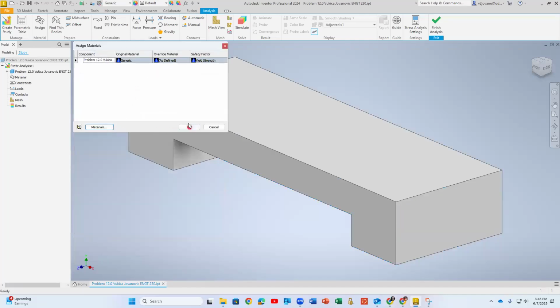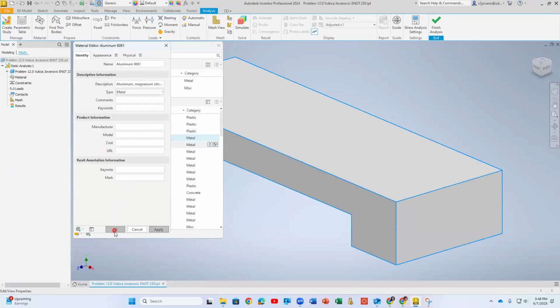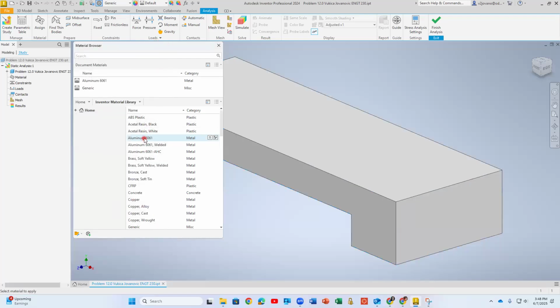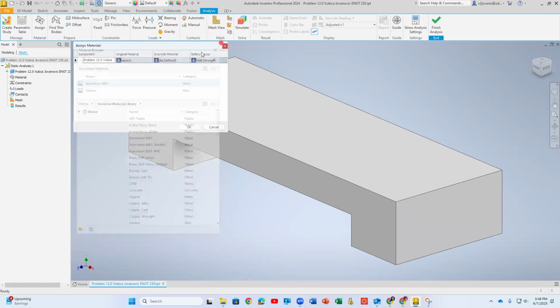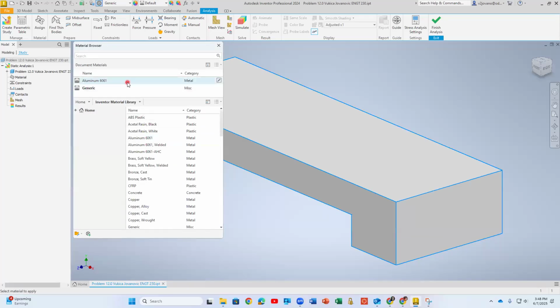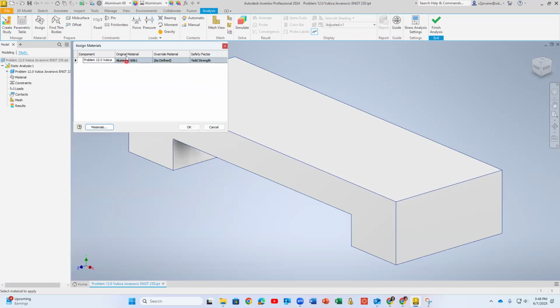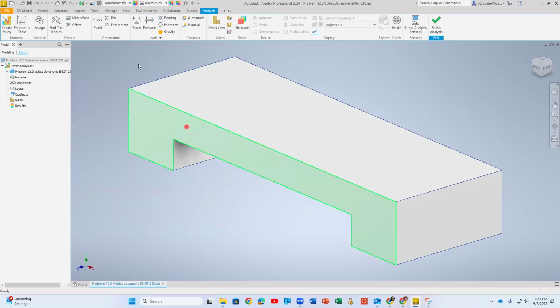And then, you see right now it's original. Well, I didn't define it. So I think you have to double click and say apply or okay. Yeah, now this one is the one that we have. It still didn't show it there. So materials, aluminum. Yeah, now it's showing me aluminum. So when you see here original material, then you can proceed.